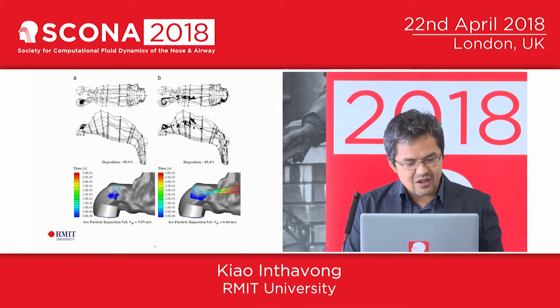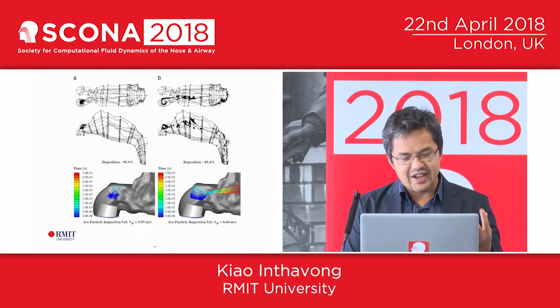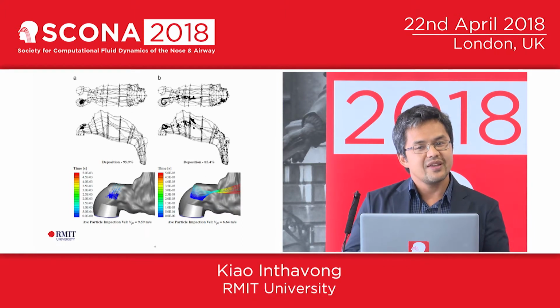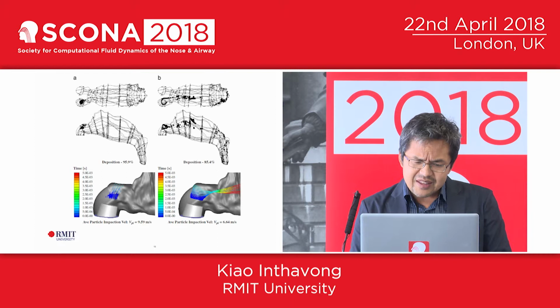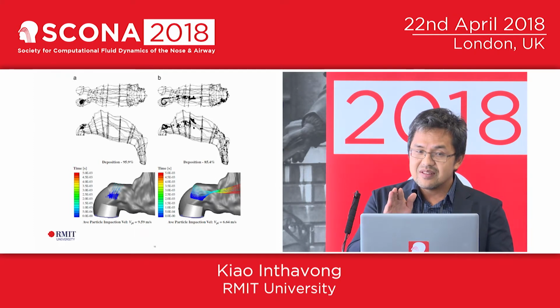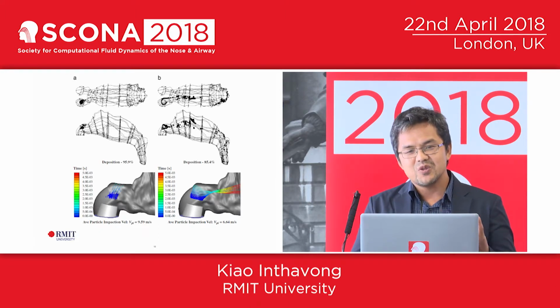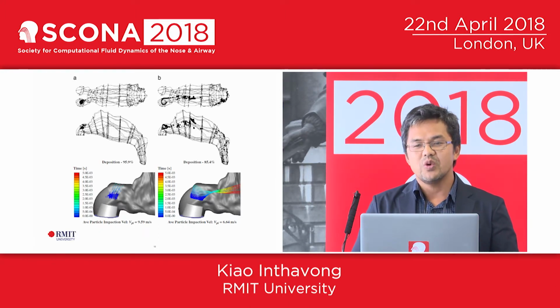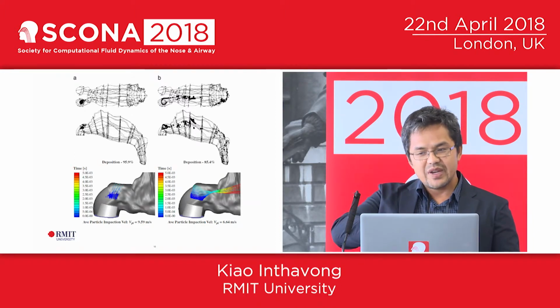And while I'm talking about this, I could also talk a little bit about the airflow distributions and how that is created from, I guess, this almost perfectly designed nasal cavity geometry. So, for example, in the front of the nostril, you've got a 90-degree bend. And with 90-degree bends, you've got a filtering function. So the nose is designed to filter particles out. And large particles in the micron range will exhibit inertial effects. So if you've got this 90-degree bend, particles larger than 20 microns will basically hit the top of the nostril.